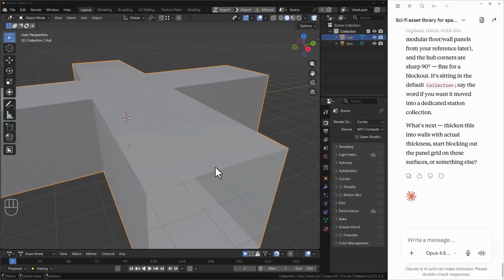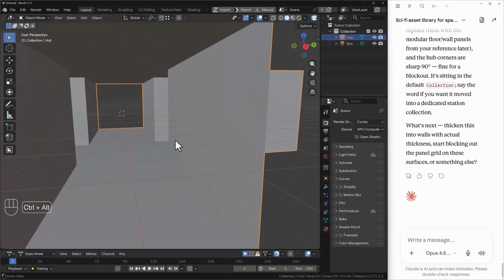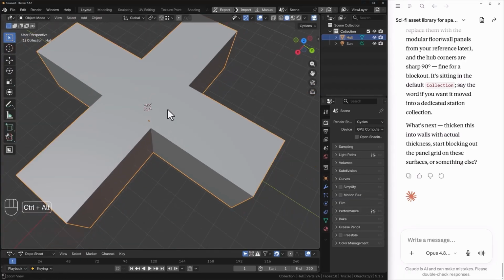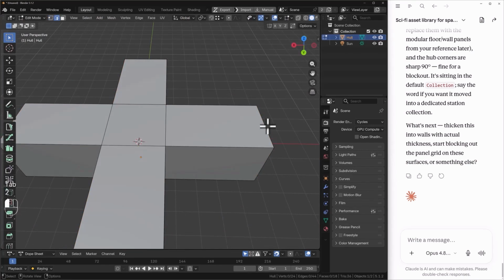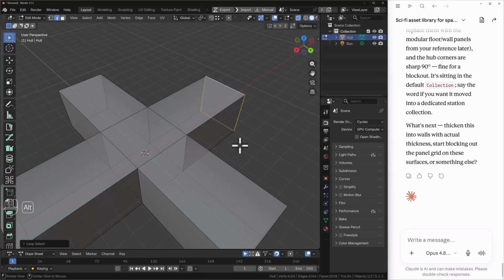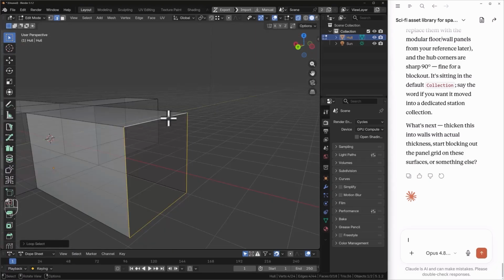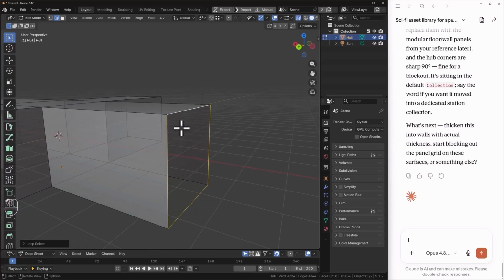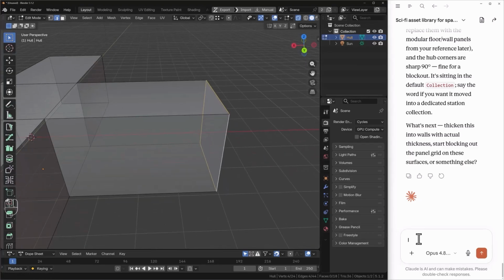The next thing would be possibly this edge to spin while being extruded. So we'll probably just want to spin extrude it at 45 degrees. All I need to do is just double click on it to select it. If you cannot double click to select it, just click on it and shift click on the 4 edges. That's it. So let's tell Claude to spin extrude it at 45 degrees.